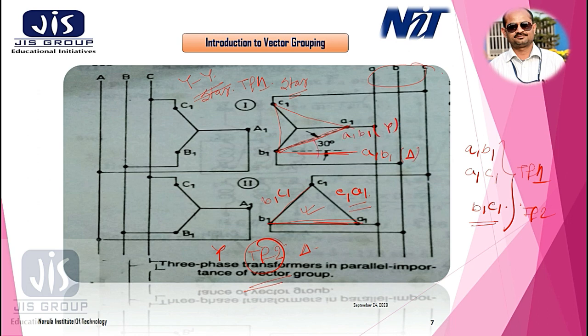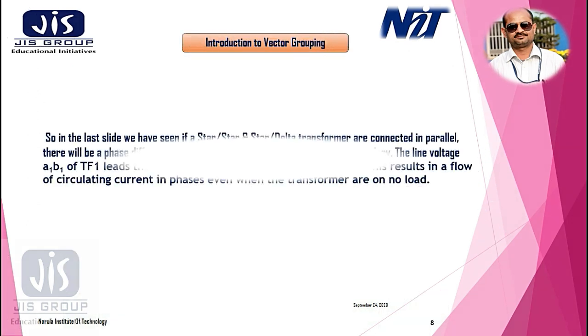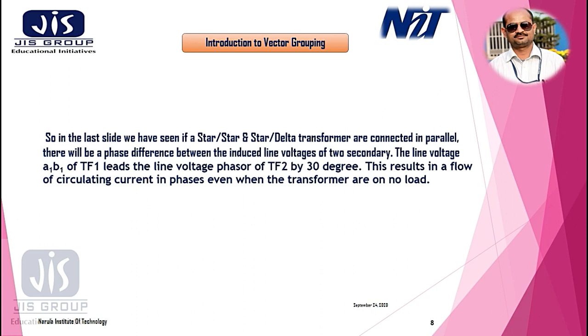So you see there exists a 30-degree phase difference, and this phase difference is responsible for the flow of circulating current. Okay, so that is what we have discussed. So this results in a flow of circulating current in the phases even when the transformers are on no load.